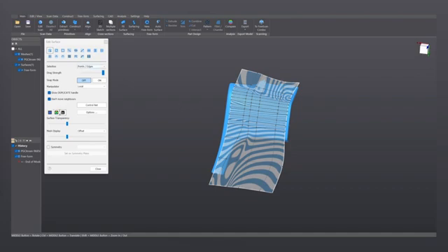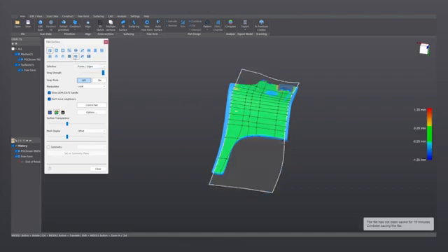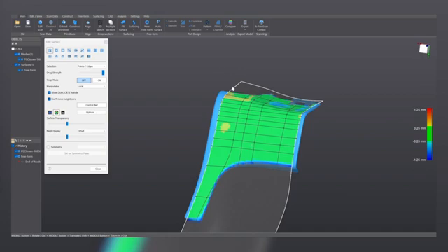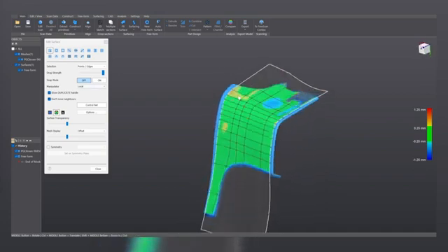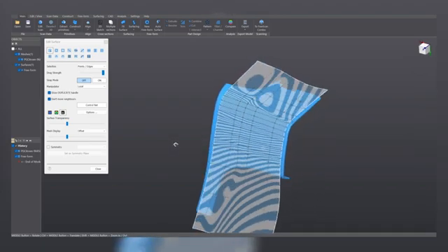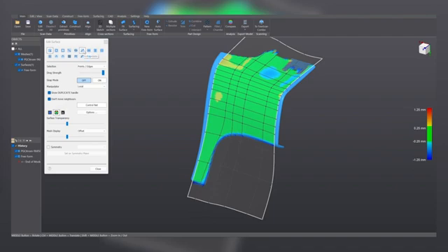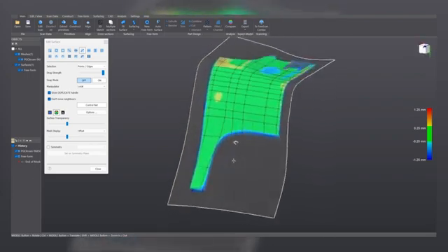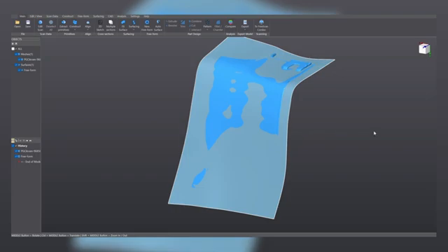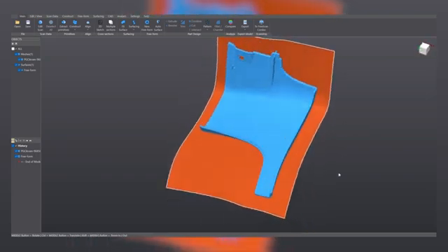To improve it, we can give it some clicks here on the smooth tool, and by compromising the tolerance a little bit, we obtain a better surface quality. Okay, so with that, I believe we have obtained a really nice surface, and let's extrapolate it towards the side in order to cover it completely. And with that, we are done with the first freeform.